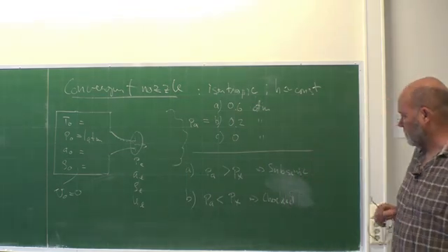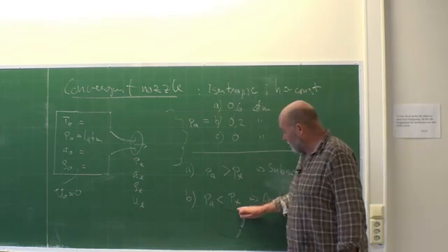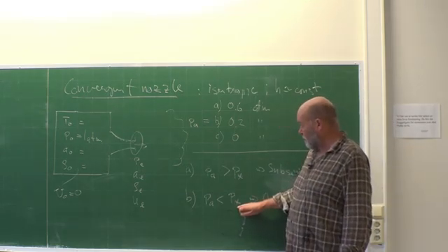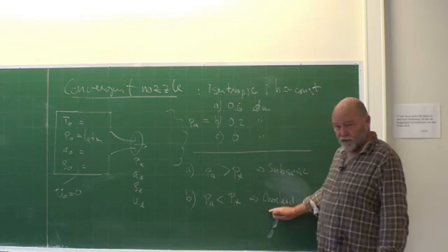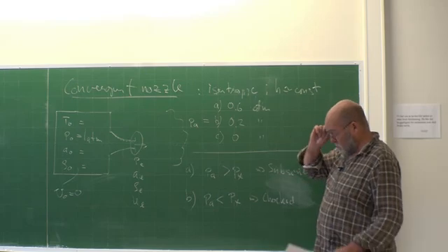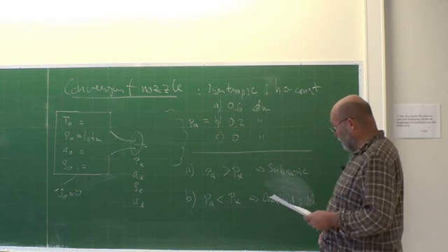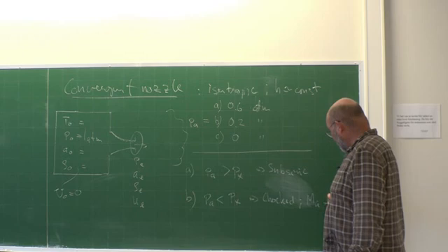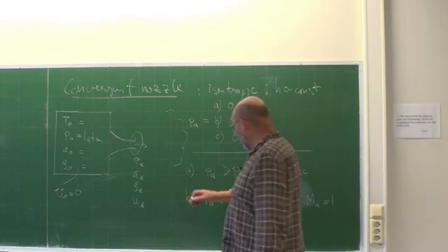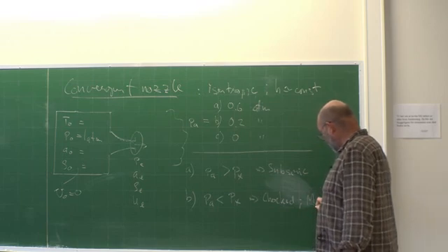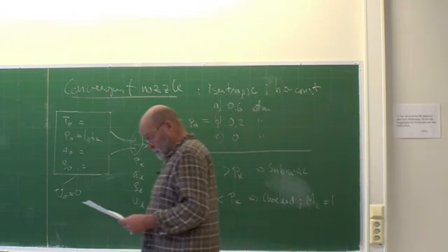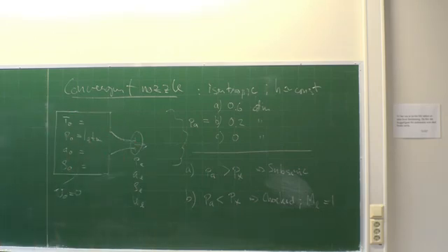Well, as long as you go below this P star here at the exit, then you will achieve Mach number of 1 in the opening. And you can't get any higher. Choked. So the Mach number is 1 at the exit. Maybe we should call it Mach exit. It will be really choked.